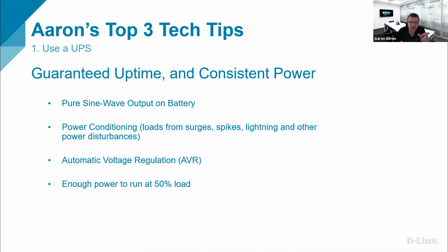And at least when you're putting in a UPS, definitely spec it so you're running it at 50% load. It's no use running it at 100%, kicking it over to batteries, and you've got about 2 minutes worth of power out of it.